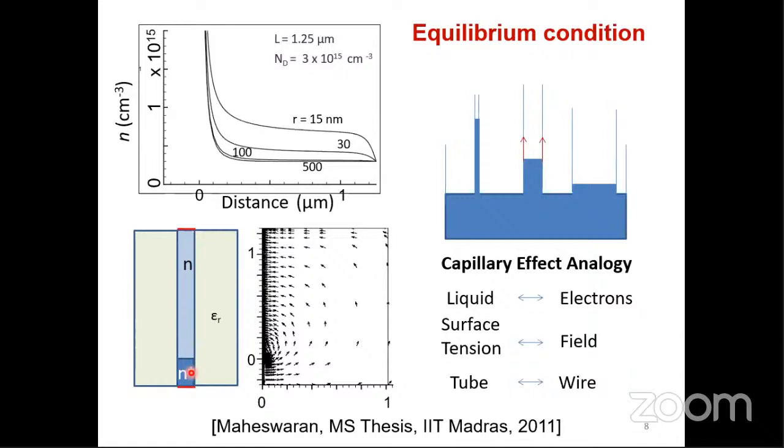Here, highly doped means electrons will be moving. Always charges move from high density to lower density. So from down to high, it will move towards upper. Electrons will be moving from higher concentration to lower concentration. So electrons will move like this. And once electrons are moved, why is the field created now? Can you tell? Sir, the positive mobile ions which are left uncovered due to the doping.